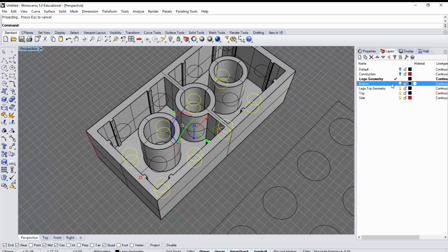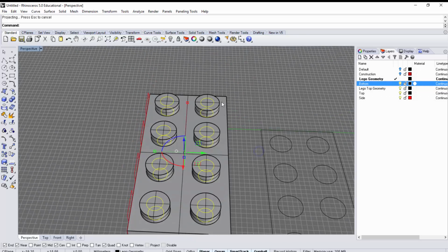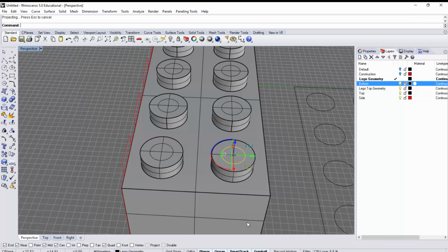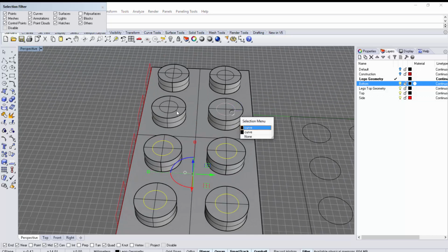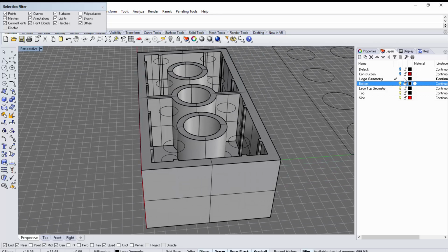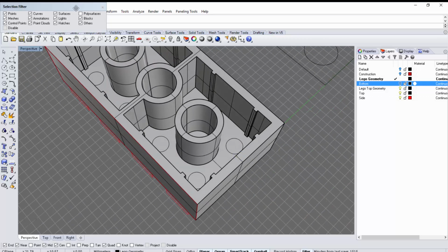Fortunately, since I've got well, let's just go ahead, and to remove some of the confusion, we'll just grab the curves. Again, you could, if you want to, turn on your filter and deselect polysurfaces, so you can just select things quickly. Make sure you get the top one. And we'll just delete these guys. And I'm going to hide away the bottom geometry again. So now we're just left with these circles. Actually, we can just leave our poly surfaces off for now.